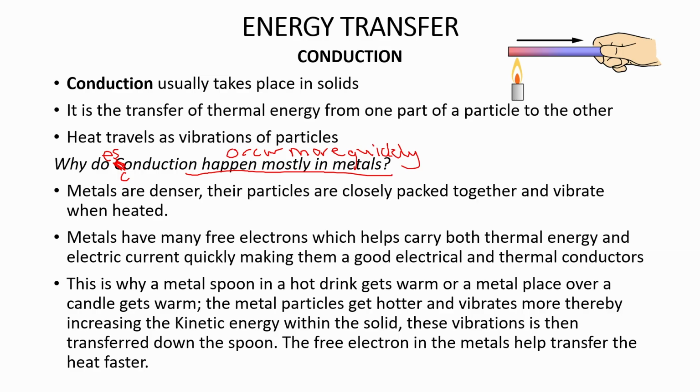One thing I quite often do when I'm teaching this topic is, before I get onto conduction, I talk a bit about the laws of thermodynamics and this idea that heat energy always goes from hot to cold. That's really useful when we start comparing conduction, convection and radiation, because when you're talking down here about being transferred down the spoon, actually the direction isn't up or down the spoon, it's from the hot end to the cold end.